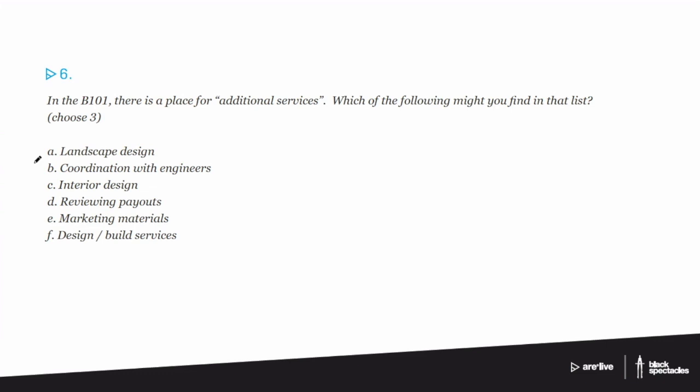So first off, one that I want to remove right away is that we're definitely not going to be including design build services in additional services. The reason for that is it's an entirely different project delivery method. You wouldn't use the B101 for that. The B101 is not set up to be a design build contract. It's set up to be an owner-architect contract. If you want design build, it changes literally every word in the contract. So you just wouldn't use a B101 and then add design build as an additional service.